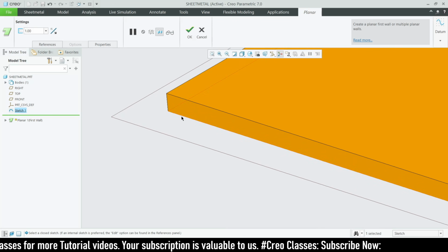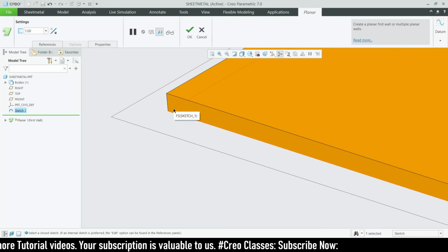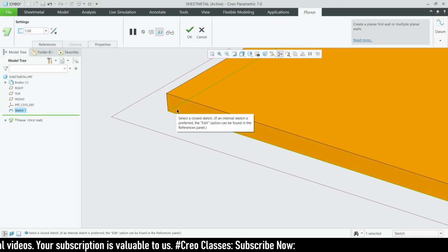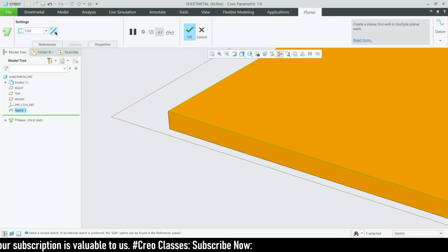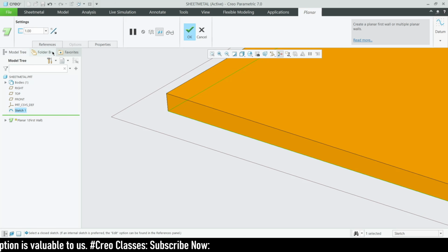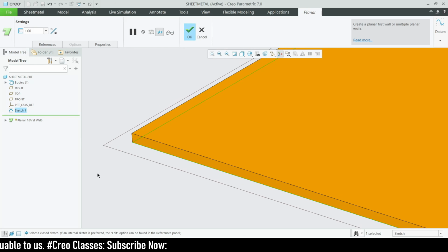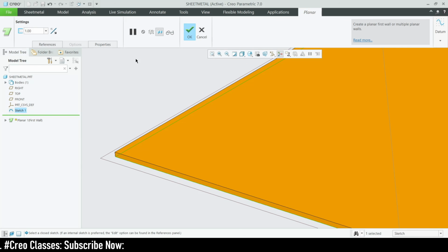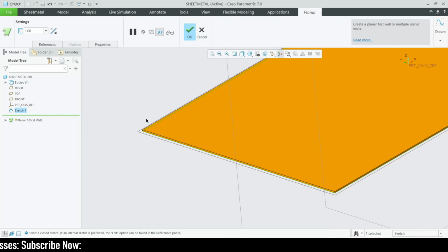You can see, this green line is our sketch, whether you need this extruded towards upside or downwards. Okay, so this is what it means. So let it be on the upper side. Here you can't use this as a mid plane. Okay, so that's the difference here.